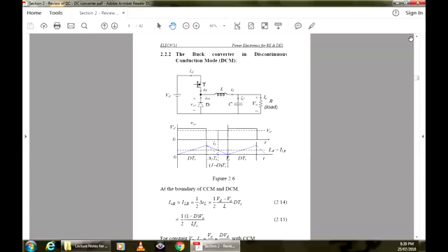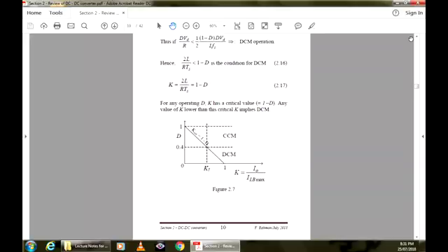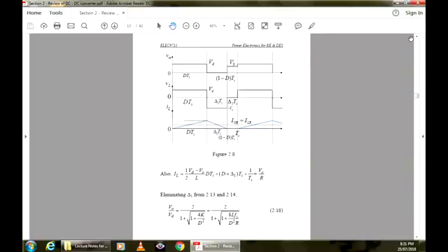But anyway, theoretically, if the current becomes discontinuous, there is some analysis which I will leave you to do, and it's not difficult. If you have understood the waveforms and how we analyze this circuit, you will easily find that with discontinuous conduction, the converter characteristic is like this. V0 over Vd is given by this formula. So it is quite nonlinear. It is no longer D here. It is 1 plus root over 1 plus 8 L Fs over D squared R.